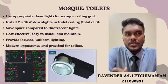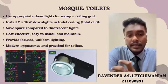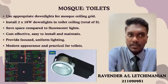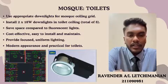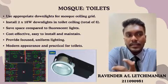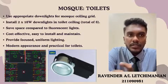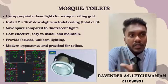We plan to use appropriate lighting for the ceiling because the bathroom grid can accommodate 300 by 300 mm in the mosque. Therefore, we use a downlight at the plaster ceiling in the toilet, 2 times 18 watt. We use a total of 8 downlights for the toilets. This can reduce the space the lighting takes at the ceiling compared to normal fluorescent light.